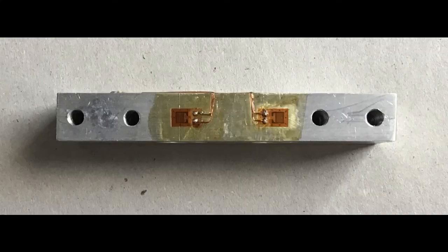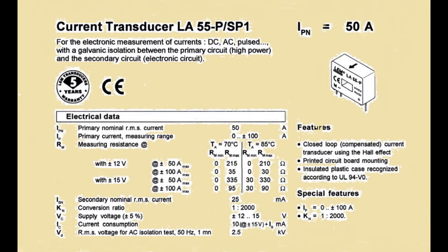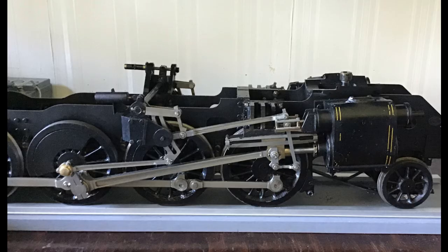At one point I considered strain gauging the two drawbars and designing the electronics to proportion the pulls. However, I decided that that was unnecessarily complicated. For the 9F, why not just monitor the loco and tender currents? As we know, these are proportional to torque. This was easy to do with Hall effect current sensors. It would not be as accurate as measuring the drawbar forces directly, because the sources of friction in the loco, with its plain bearings and linkages, would be significantly higher than those of the tender.